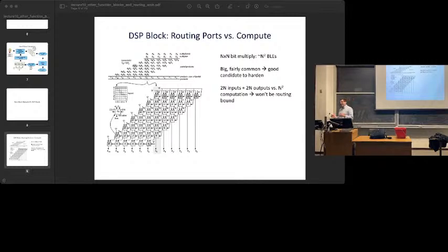And we care about multiplications. The most important multiplication historically in FPGAs has been about 18 by 18, because that's about enough for wireless signal processing and filtering in that application. 18 is pretty big. So 18 squared is a pretty big number, so it's actually a fair amount of logic for an 18-bit multiplier. So that's good.